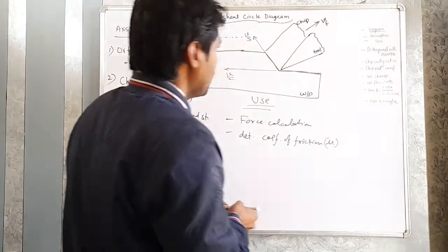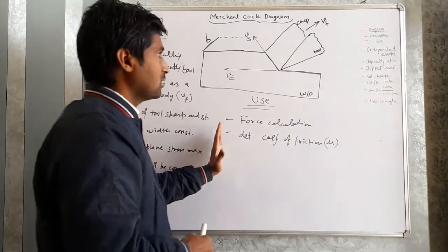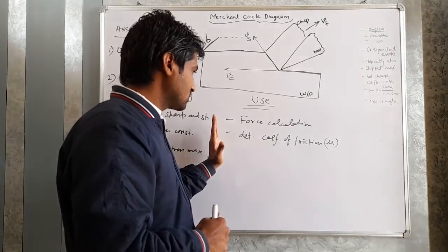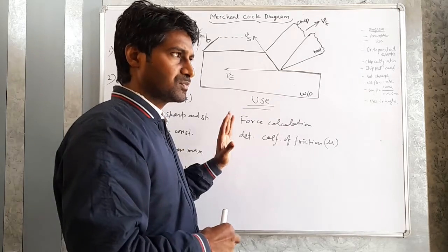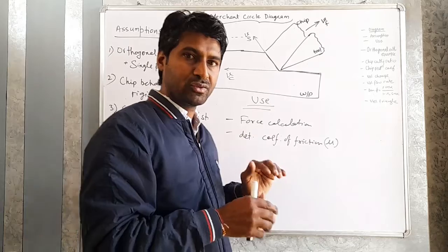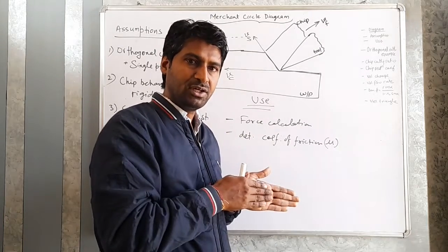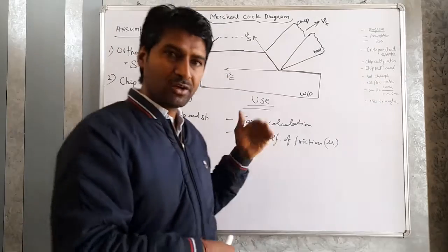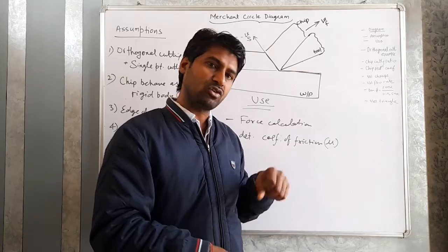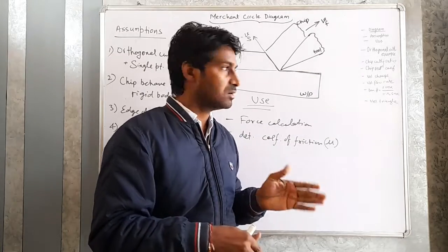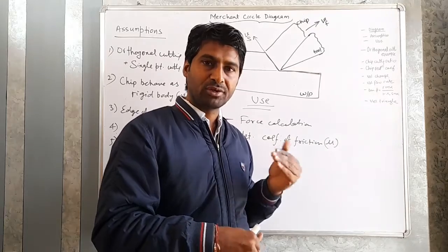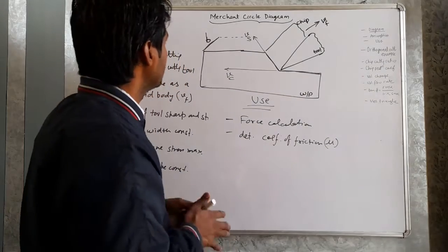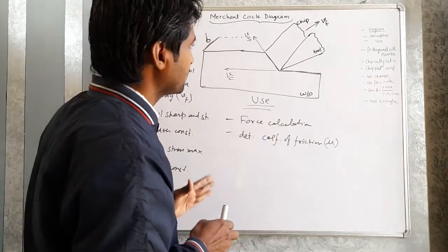Next, I will discuss what orthogonal cutting is. Orthogonal cutting is the type of cutting in which the cutting face of the tool is at 90 degrees to the line of action or feed motion, and it is a 2D type of cutting in which the radial force will be 0. Examples of orthogonal cutting are slotting, parting, pipe cutting, and grooving.